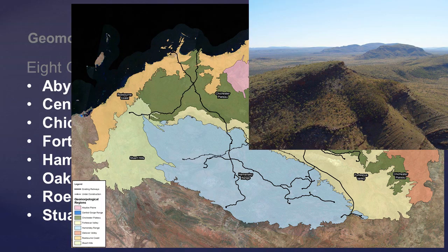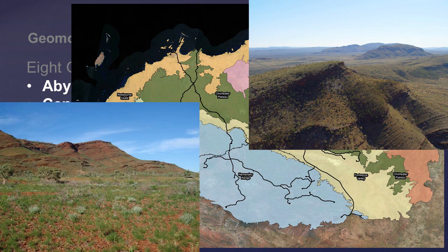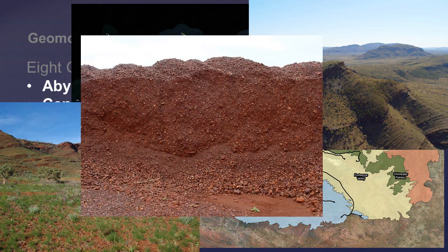The Hamersley Range occupies the southern part of the Pilbara Craton and is distinctly different from the Abydos Plain unit. There are several mountain ranges that are comprised of banded iron formation, dolomite, shale and some volcanic rocks. Previous road and rail projects in the Hamersley Ranges traditionally use colluvial gravels which originate from BIF ridges where the coarsest material is generally found near the top of the slope and the material becomes finer towards the toe.